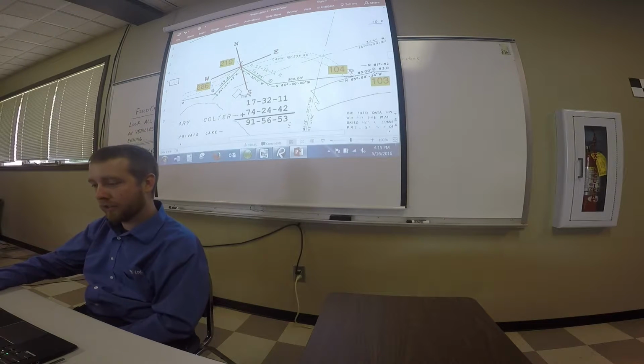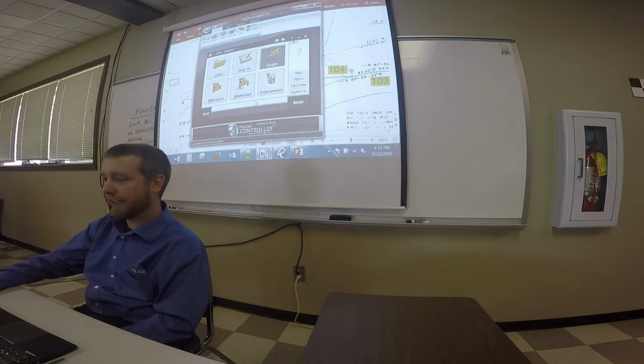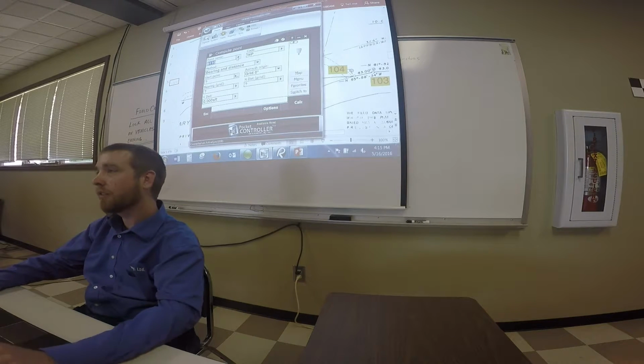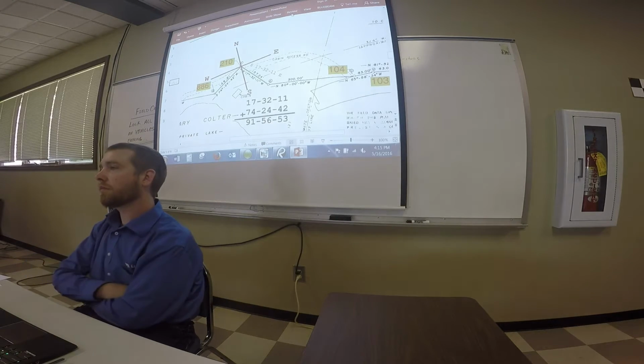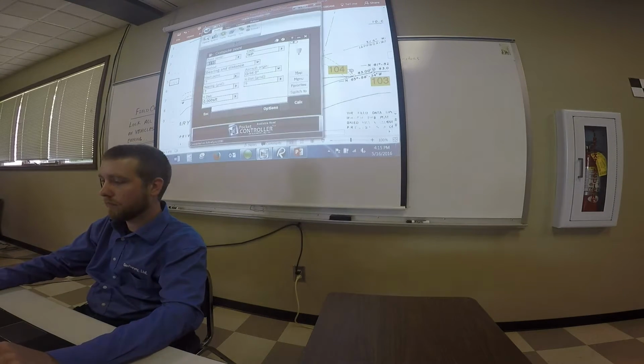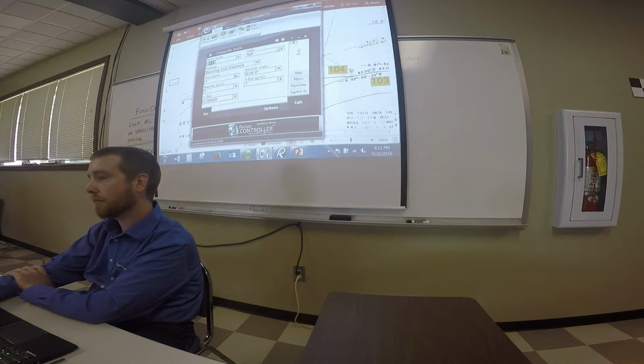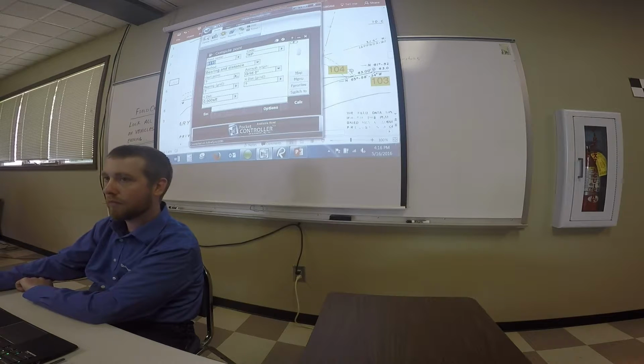Anyway. Okay. Now that we've found our angle, we'll go to the data collector. We'll go to COGO, compute point. I'm sorry, I'm jumping one more time. So everybody understands what we're doing here: the reason we need this angle right is because you can't use that bearing to create the coordinate. Why can't we use that bearing? We could, but we can't in this case. Why? Feedback. Are we not on the right datum? Correct.